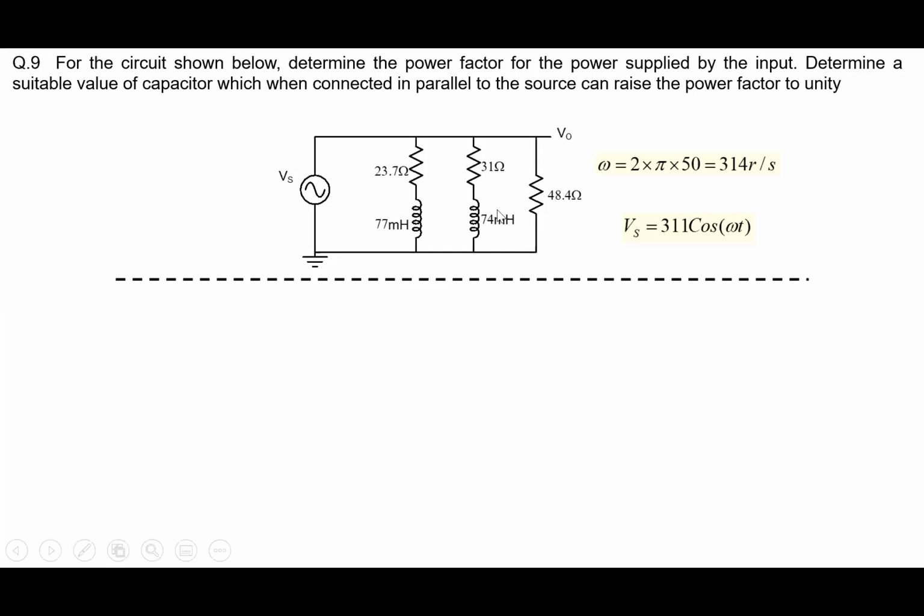So even though you may not be consuming it, power is not dissipated there, but you're drawing current. You're drawing current, and that current leads to losses in the transmission part here. And therefore, it's not a wise thing to have a power factor which is very, very small, because you're not consuming anything, but you're drawing a lot of current, and that's a waste. So that's why what we are trying to do is calculate the power factor.